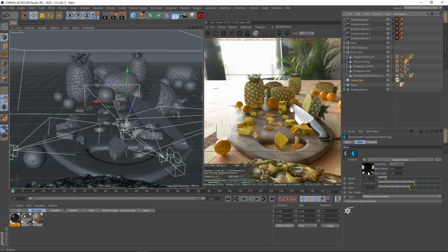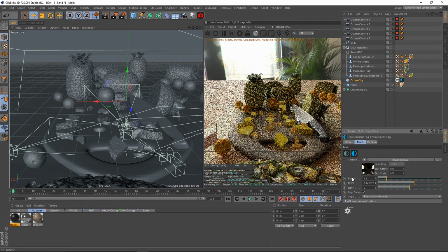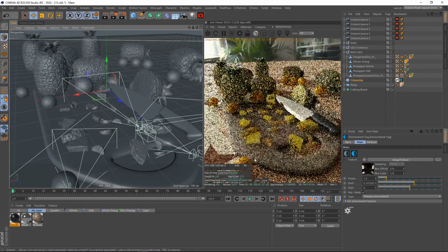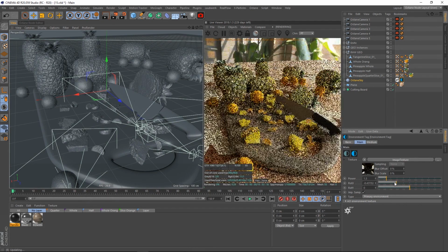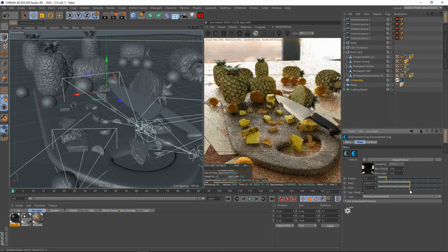With this HDRI environment, I used a Grayscale Gorilla HDRI, part of the Grayscale Gorilla HDRI pack, and I upped the brightness to 1.3. The reason is that a value of 1 just felt a little too dark. I wanted a little more brightness, a really bright scene, and then I simply rotated the HDRI until it felt like the light was coming from a good spot.